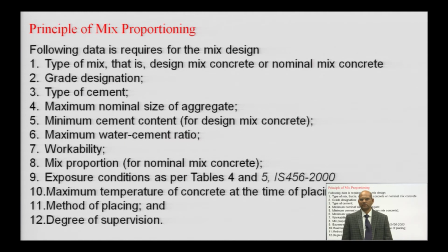If the degree of supervision is not good, what will happen? Quality of concrete may deteriorate, so the standard deviation will be more. If the standard deviation is more, then to achieve, say, M40 grade concrete, you have to increase the mean target strength to achieve that particular grade of concrete with compliance criteria.